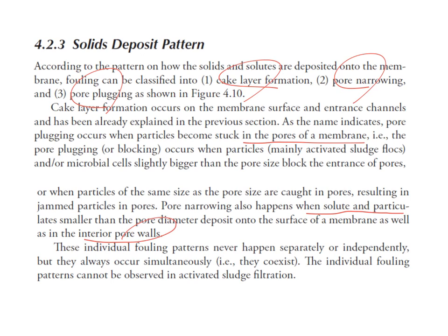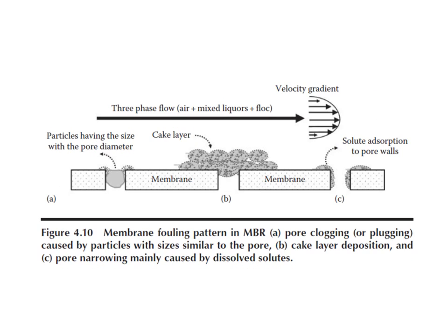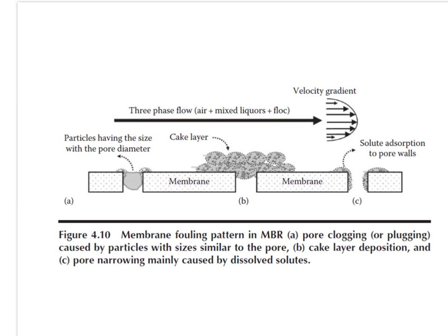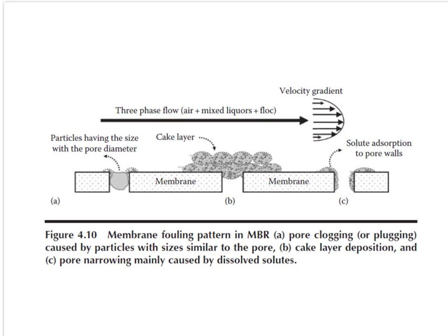When we consider the MBR, the individual fouling patterns cannot be observed separately. These are the schematics of different fouling patterns that I already explained. So if we have a very small foulant, solute adsorption to the pore walls can be observed, as you can see just here.